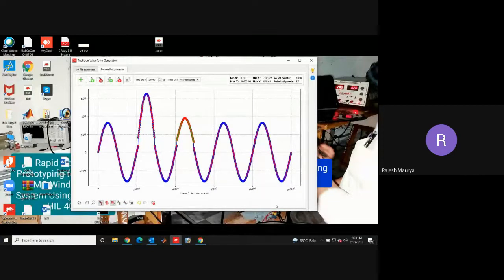Okay, so in Typhoon HIL you need to remember .tsc for Typhoon schematic editor, which is its full form. Then when we compile that model, it is generated in .cpd format, but we generally do not require .cpd format. If you want to share that model with anyone, .cpd format is not necessary. Whenever we compile, it is generated automatically in the background.